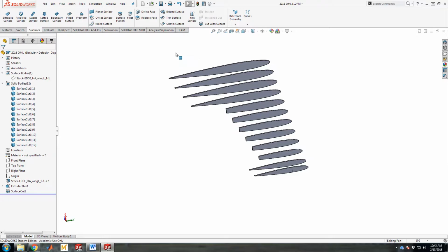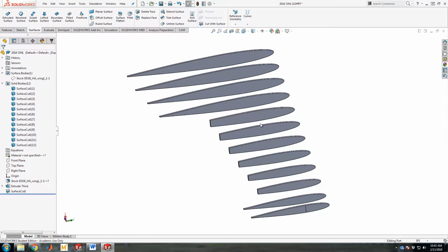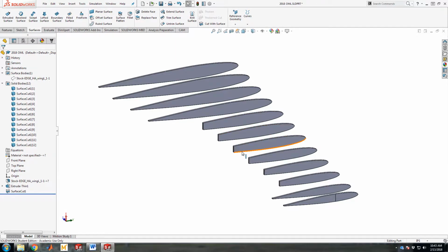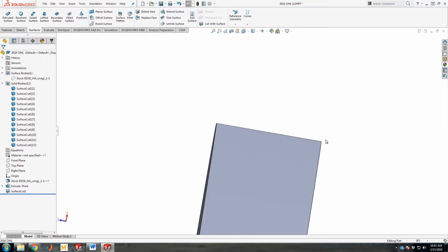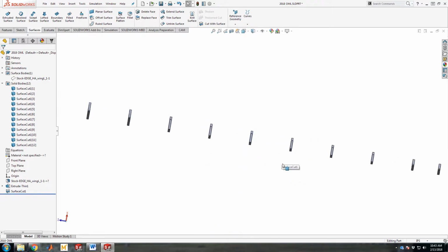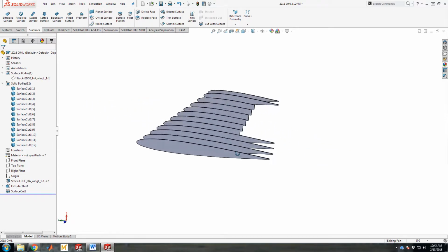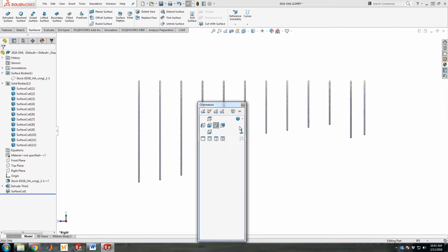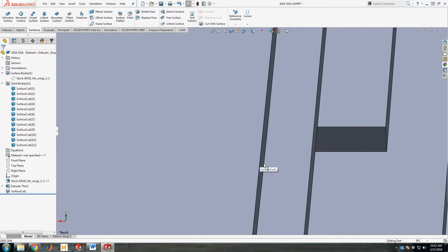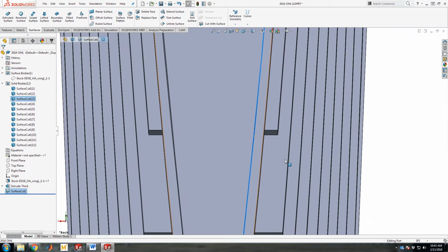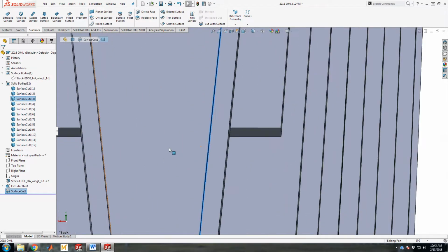But establishing these two-dimensional surfaces, well, ish two-dimensional, is what you're targeting for creation of G-code for a pattern to actually cut material. Keep in mind that this surface is still actually slanted. If you zoomed in there, you can find that this wing is contracting as it goes out towards the tip. So these are not pure two-dimensional shapes. If you view it from the very end, you can see that even for an individual rib, you see two lines. So you see some projection of that surface as it's slanted.